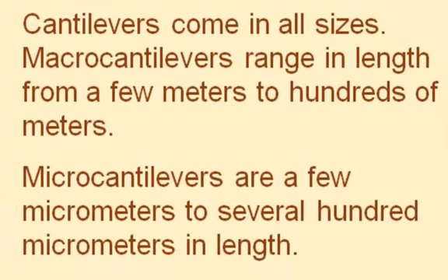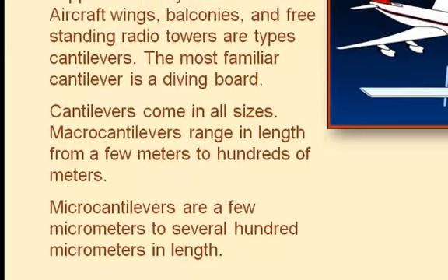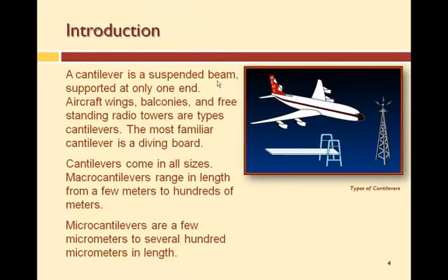They come in all kinds of sizes, and you can change the properties of how a cantilever vibrates, for example, by changing properties such as length and thickness, adding mass to it, using different materials. Micro cantilevers can get very, very small, in the hundreds of microns or smaller in length. Okay?